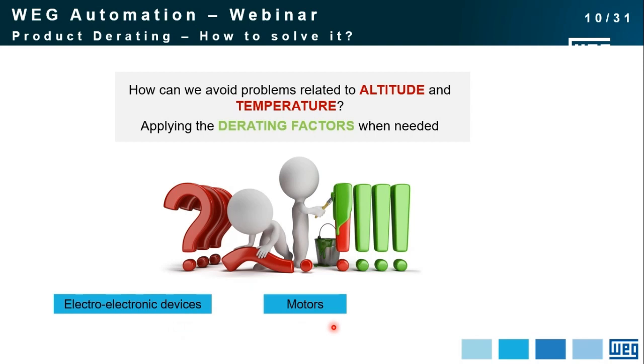Another topic I want to say is that the motors, most of the loads that I'm going to use as applications here, I'm not going to derate. I will already consider that it was already derated, as motors have an advantage compared to other electronic products or components. Electric motors can have their frames increased, or you can use bigger frames for the same motor. This way you can improve the heat dissipation of it. So they have a plus compared to other components.